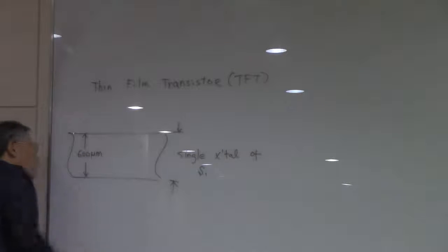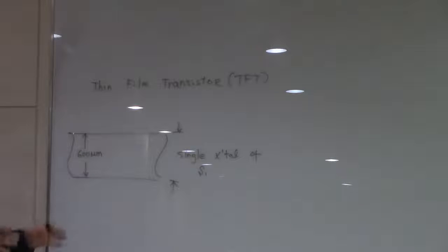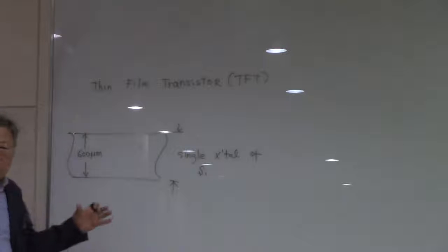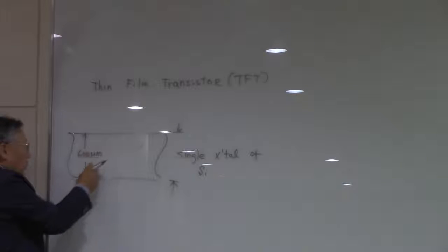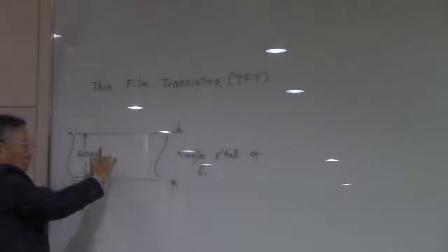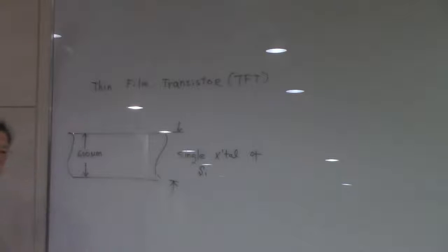Mostly it is 600 microns these days because the wafer becomes very large, like 12 inches in diameter. So that's huge, and if the thickness is too thin, then it's going to be twisted during the heat cycle, warpage things. So we have to keep this thickness above a certain thickness, and normally it is about 600 microns.